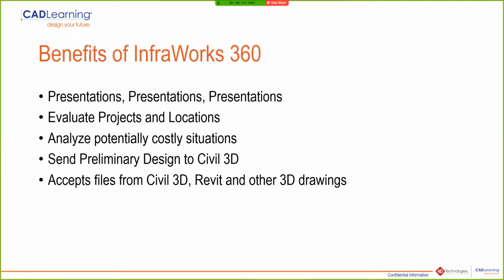With InfraWorks, once you get it into InfraWorks 360, you can analyze any potential issues that might be costly. Just because a client wants to do a subdivision or a road in this project doesn't mean where they think it should go is the best option. And this gives you the 3-dimensional ability to show them why. You can show them that there's going to be a huge cut and fill problem on the south or north side. It's going to be really costly to do that. Maybe we should shift the road in a different direction.